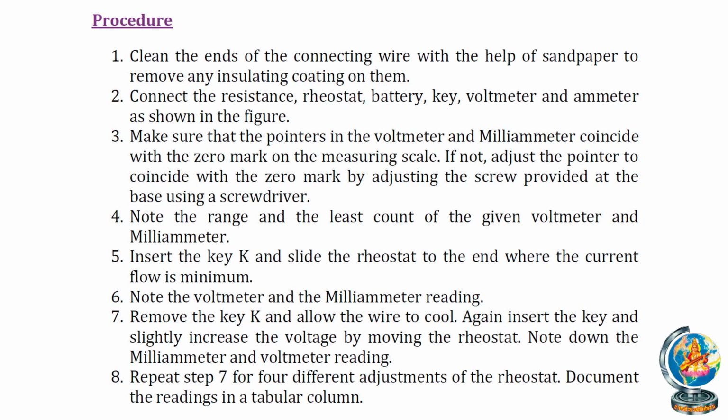Eighth point, repeat step 7 four times by adjusting the rheostat, taking different values of voltage, and you need to get the corresponding values of current. Document the readings in a tabular column, that is, put them into the observation table.